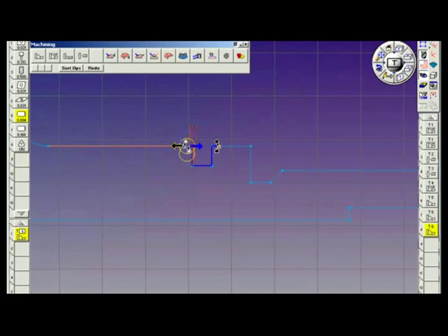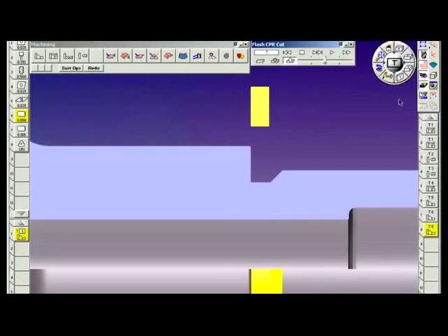When I hit the do it command, render it, and we'll single block to that cut. There it is. Corner break, exit, other side, corner break, cut, feed across the bottom, and leave the work. Show the geometry, and we can see that we've cut it right to the line.